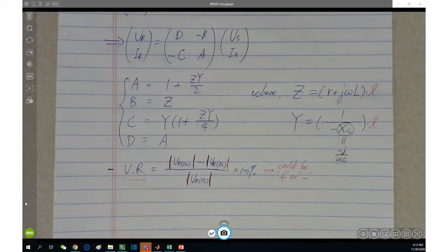Why do you need the reactive power compensation? That is also called reactive power compensation. Why do you need it? Because you're feeding certain load and then you're losing reactive power. Losing reactive power, your voltage can drop. To hold this voltage back up, you need to compensate the reactive power. Okay, this is a very regular action in the power system control room.